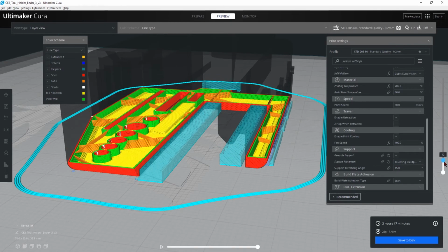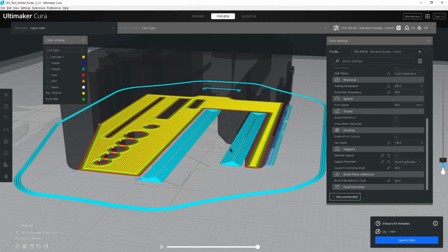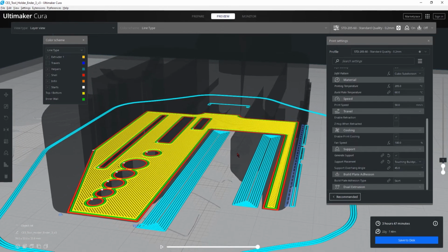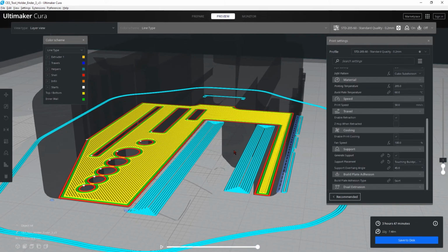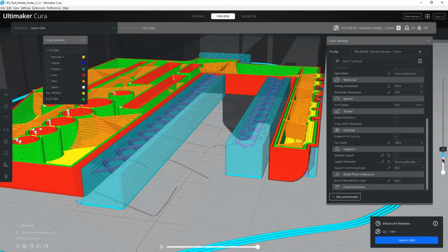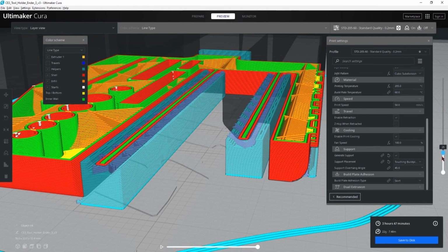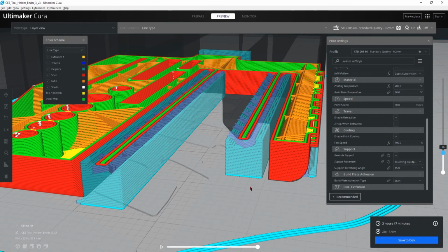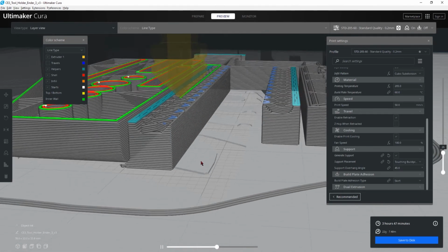Now at layer 1, there is more cyan or helper lines showing the support lines that will print underneath the floating bit of the model. Going up the layers shows the support going up and just about touching or supporting the floating bits. This gives the plastic a place to print on instead of over air as shown by the darker blue lines. Now the model is supported and should be ready to print. I'll watch this play out again to showcase that now the model will print over the support structure as I